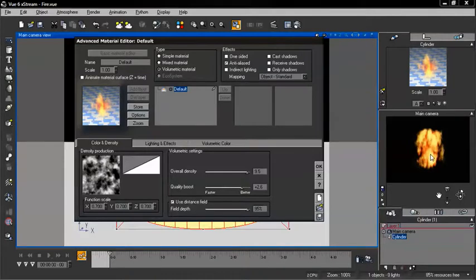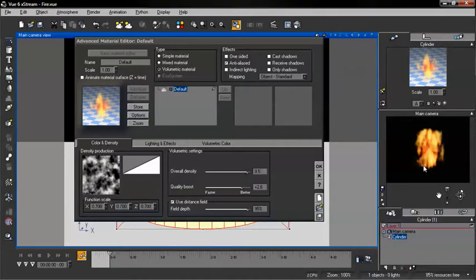We can also increase our quality boost even higher, and we can see it starts to take a little bit longer to render, but it starts to become more blurred, and we might need to define our density production a little bit more in order to see a little bit sharper on the edges. But we can tweak that a little bit later. I'm going to turn our quality boost down to +1, and now we can start to see some of that detail coming back, mostly being represented as sort of a grain.